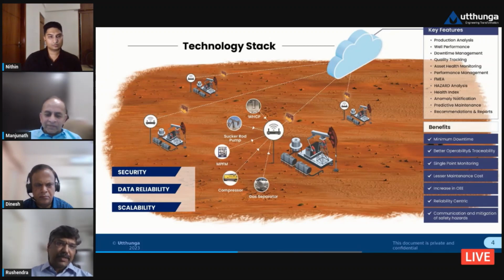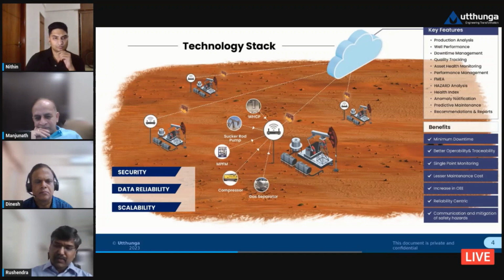And there is no dedicated communication or anything that we have sought for this particular implementation. We are running on a regular cellular network, and it has its ups and downs. So we need to deal with that. So we have provided comprehensive infrastructure within every edge to make sure that the communication is managed properly. So if there is a disruption, then we are going for store and forward kind of features. And when the edge comes back, or when the communication comes back, we provided multiple channels to stream both the live data and your historical data at the same time.